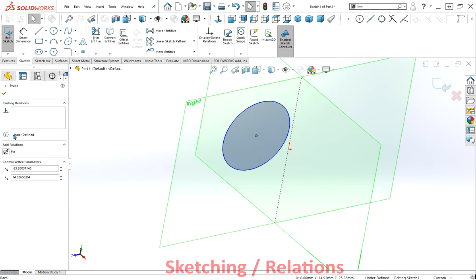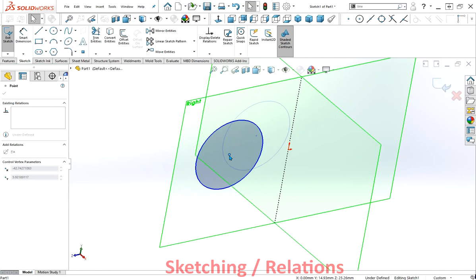And you'll see this here. It says undefined. That's because I haven't given it a size, so it could just be any size, whatever it happens to be. And other design rules that we put in could actually accidentally change that, and we might not want it. And also it can be positioned, it's not fixed in space, so that's definitely underdefined.